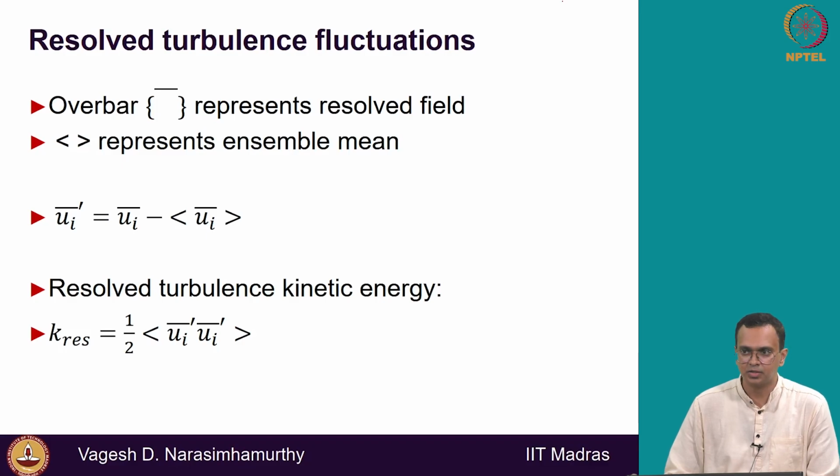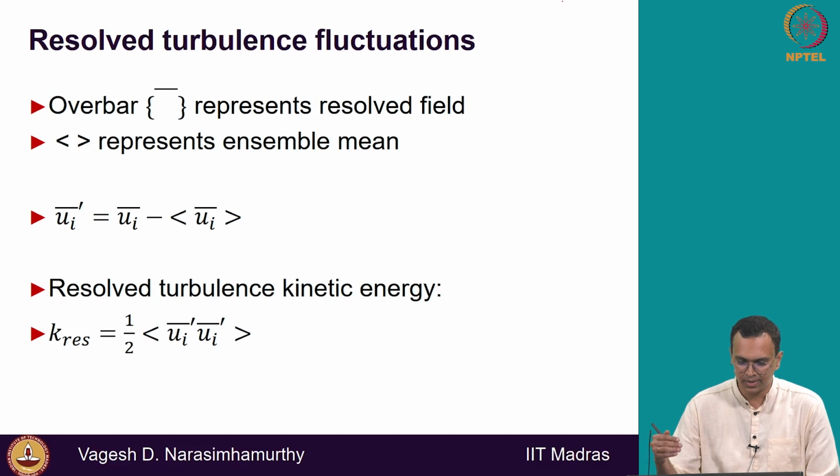So in the last class we looked at large eddy simulations, various SGS models basically, right? Smagorinsky, dynamic Smagorinsky and scale similarity, the three, or you can say two classes of models. And I'm just going to summarize a few things that can be useful. And this particular slide tells you about what happens after you compute your LES calculation.